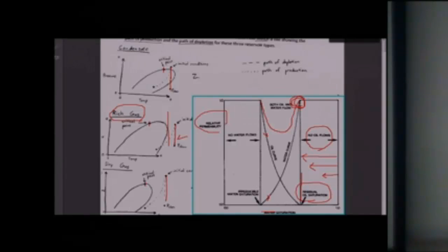Look, see that? If we're in the oil region, there's no chance that we're going to miss the bubble point, the saturation pressure. We're always going to go into a two-phase region in an oil reservoir. In a gas reservoir, we have a chance of missing it. So yeah, that's the ideal situation. Get a lot of liquids and get a high recovery.